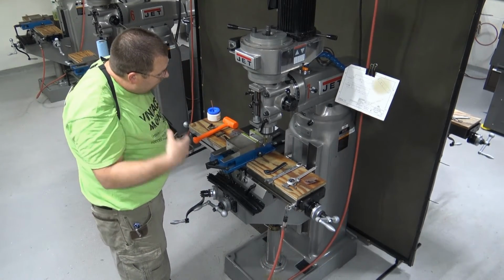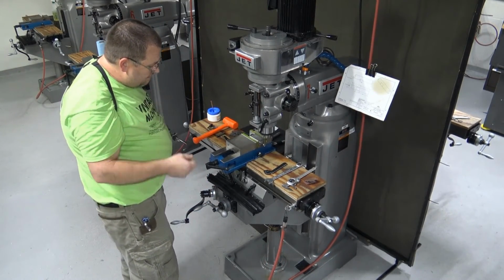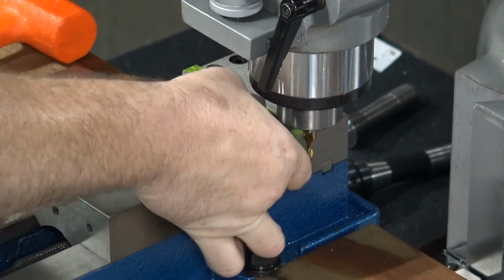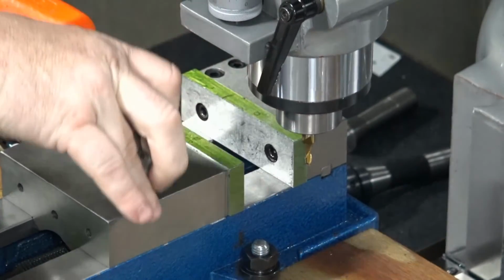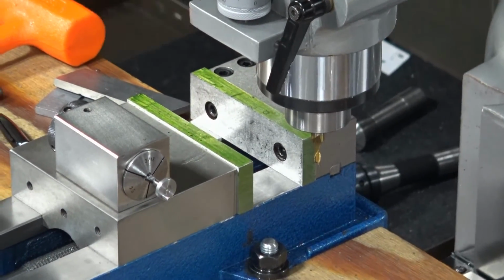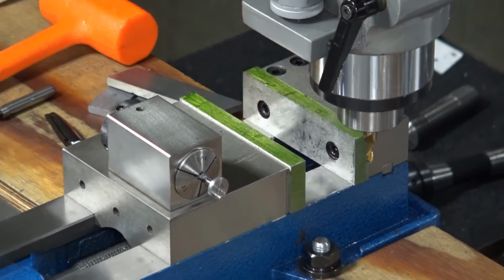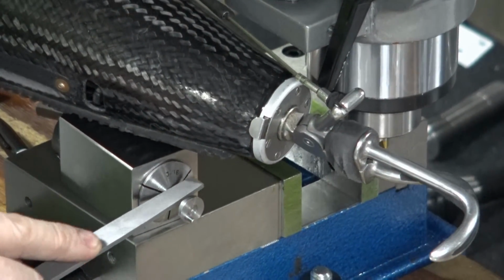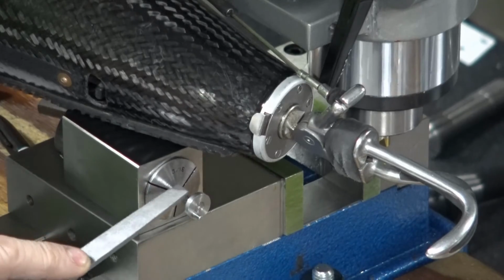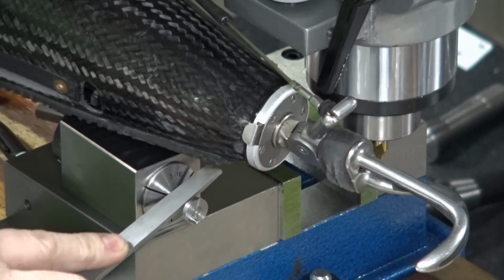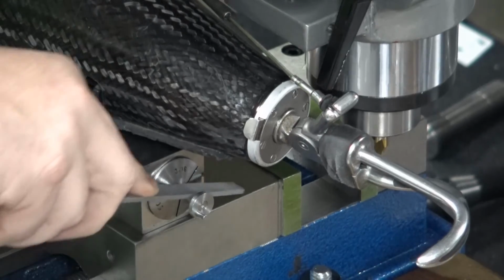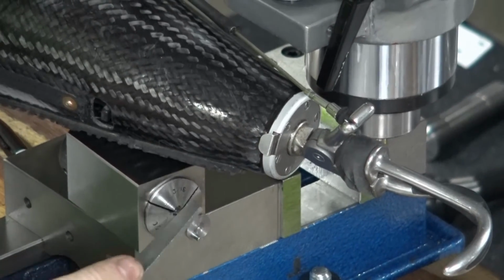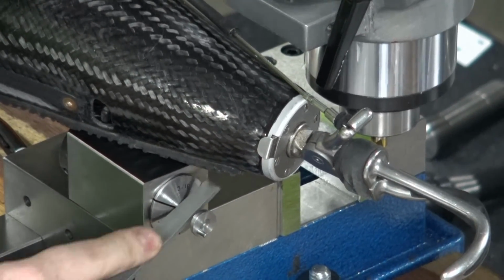Okay, so now I've got my flat put on. The biggest issue that I have to take care of right now is deburring it, because anytime you make a cutting operation, you can count on the fact that you're going to have some burrs. Now what I like to use to get the main part of the burrs off first is I like to take my 6-inch flat tile and just kind of roll up and over that flat. Okay? That's really all that you need to do to get that burr off,